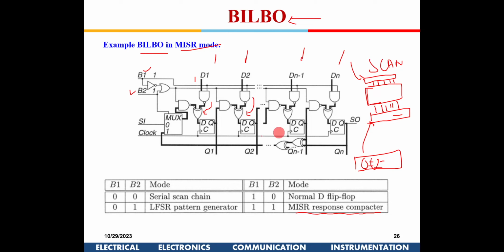Now because of all the RISC processors, they just have small blocks only. They do limited functionality. Even today, even the big processors are actually RISC processors. From the top level, you could consider that as a complex processor, but there is a compiler in between which breaks those instructions into small RISC instructions, and finally at the hardware level it is a RISC processor. Even most modern day processors are pipelined RISC processors. That means the combinational blocks will be small blocks only, which can be accessed through this scan design.